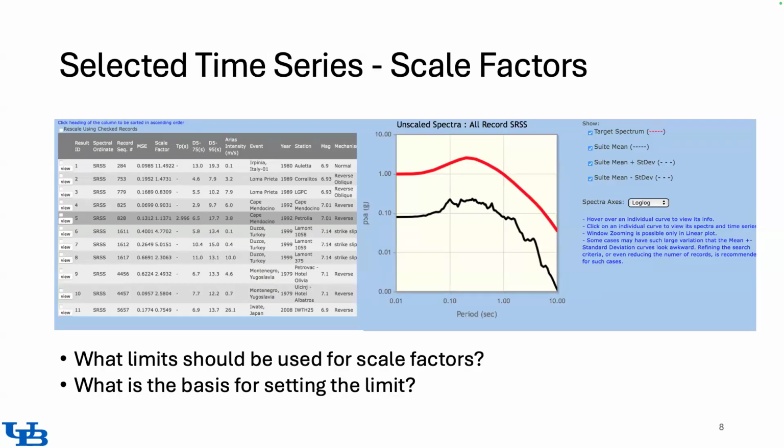There are maybe just 3 or 4 ground motions that exceeded 0.2 g. Most of the ground motions had PGA less than 0.2 g. So it was a qualitative study to conclude that in the East, we are not supposed to design for a ground motion of magnitude maybe 7 or 8, because nothing has been recorded in the last 40 years. So the probability that a ground motion with PGA greater than 0.2 g would be recorded is very, very low.